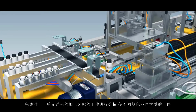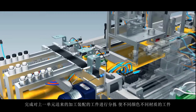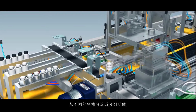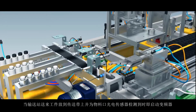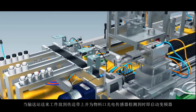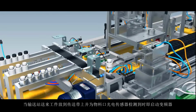The workpiece processed and assembled that was sent to the last unit is sorted, so that workpieces with different colors and materials are diverted into different feeding slots. When the workpiece delivered from the delivery station is placed on the conveyor belt and detected by the photoelectric sensor of the material port, the frequency converter will be activated.